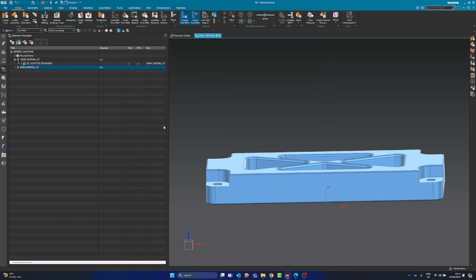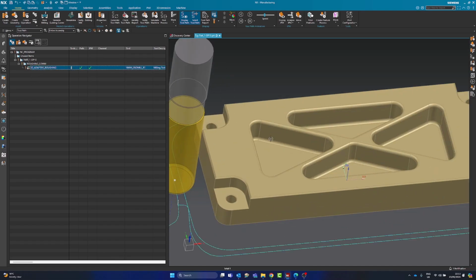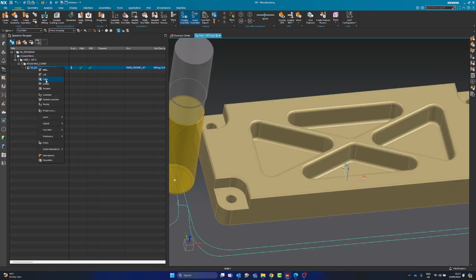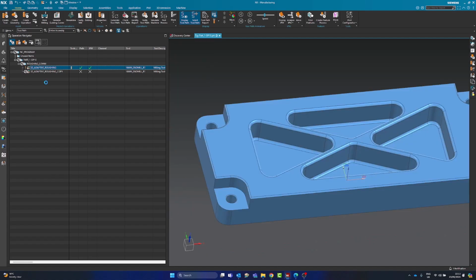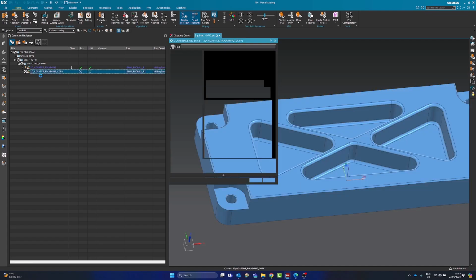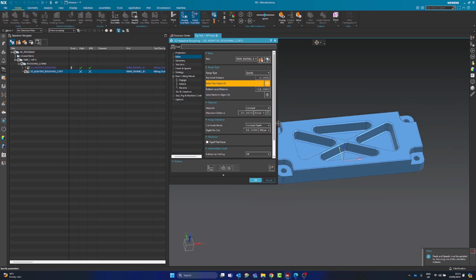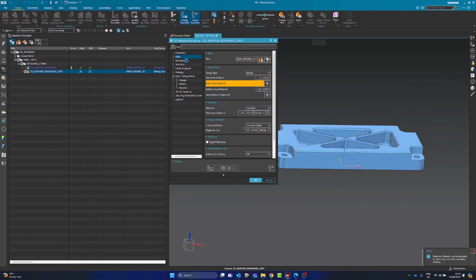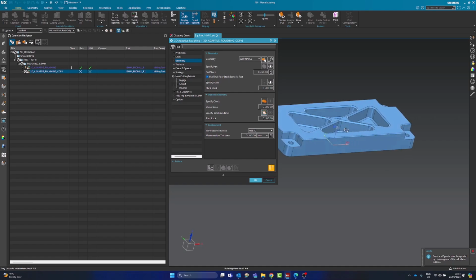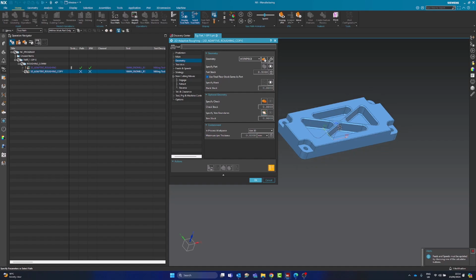Okay. So now you can either build up that toolpath again, or as you're going to be using another adaptive roughing path, I'm just going to use this and copy it and paste it. So now I see I've got the tool here, and now I'm going to go into the toolpath and change the tool from the 16 to the 6. Okay. So what else do we need to change about this toolpath? Well, it's currently looking at that outside shape. So we need to now specify the inside pockets here.